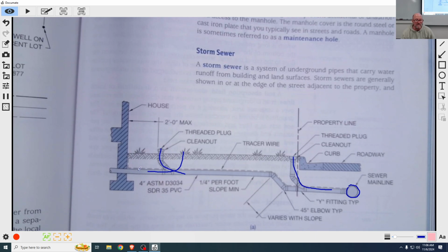So typically you've got a 4-inch PVC, and it goes into usually an 8-inch or 6-inch pipe here, and to a main sewer line that's parallel to the road. It goes down the road out to the waste treatment, right? And so this is just a storm sewer. Well, no, this is a regular sewer line. It drains out of the house, goes into the main sewer line, and out to a water treatment plant, which is like a giant septic tank.